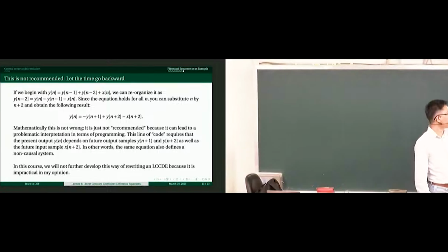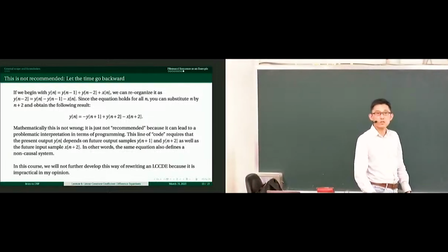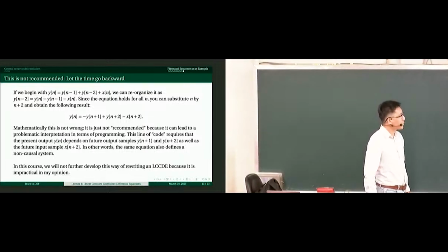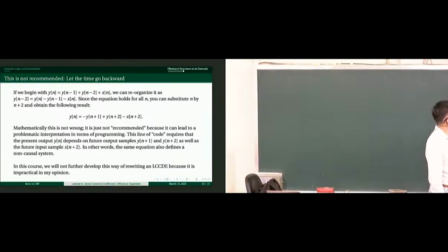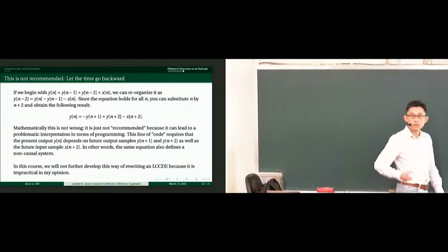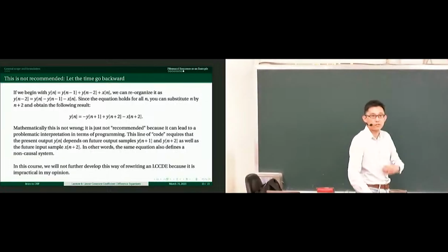this difference equation, as you know now, has an impulse response with x being the input and y being the output. Its impulse response is the Fibonacci series. Okay, the Fibonacci series, because every present term is the sum of the past two terms. So it creates the Fibonacci series as n increases, as time proceeds, right?